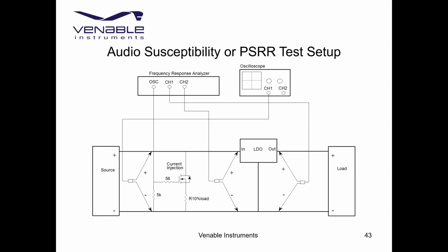And then you're measuring the disturbance on the input of the power supply and comparing it to the disturbance on the output of the power supply. Of course, you want very little disturbance to propagate through your power supply, and usually rejection is good inside the loop bandwidth. You usually get pretty good noise rejection. The loop will reject noise. This is for an LDO, but you could also use a switching power supply. You get the same measurement.